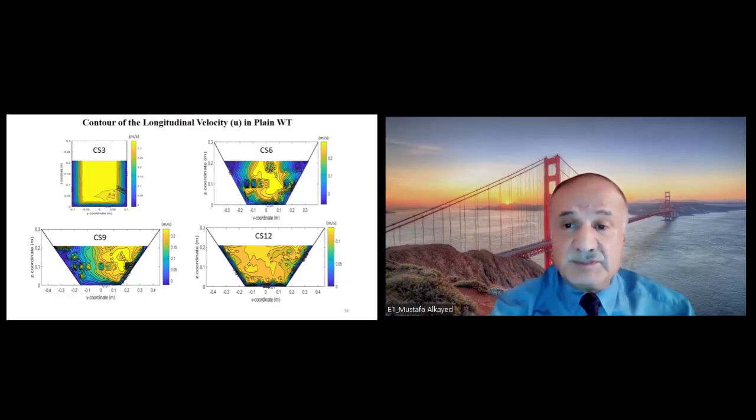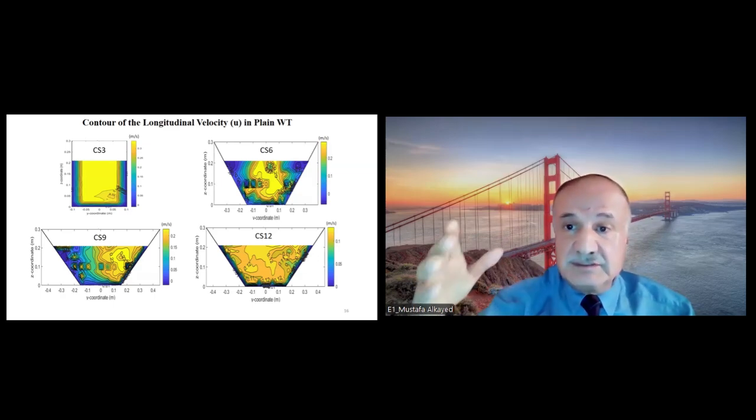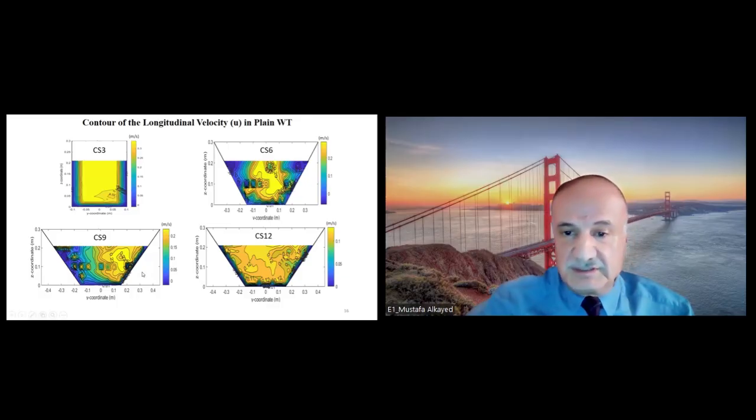Now, this flow separation forces the main flow to go to the right side. And this is accelerated and causes little separation in the corners here. But the main losses were, as we can see, at cross-section 9 in the left side, and the main flow is going to one side. This one shows the rectangular, trapezoid, warp transition, and the trapezoidal at 9 and 12.